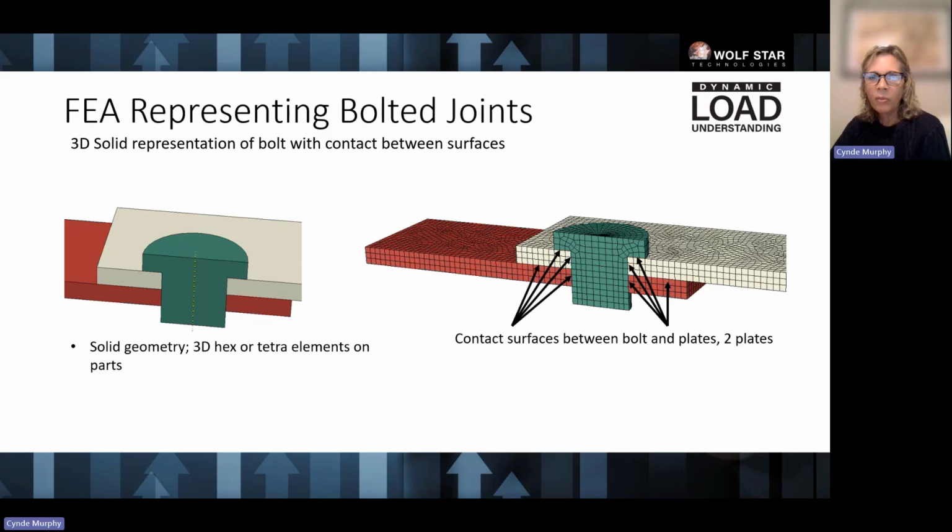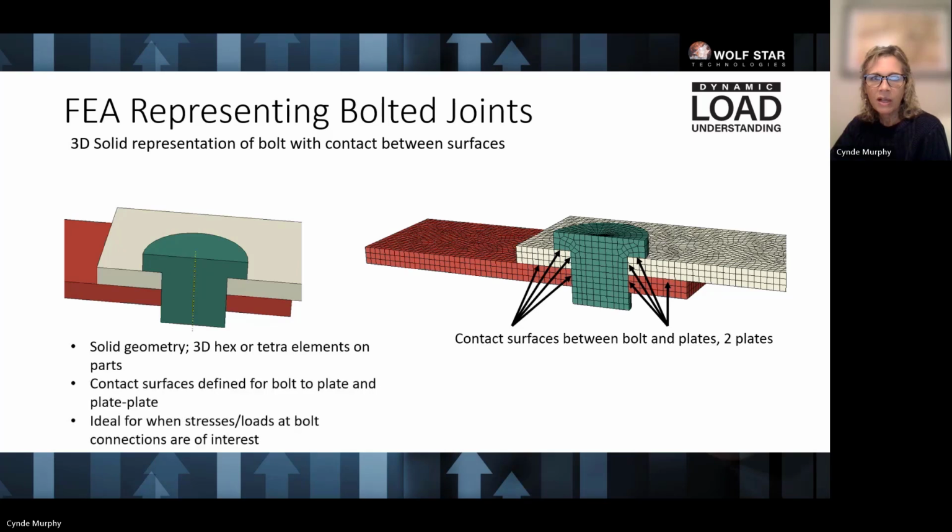All or most of the parts are modeled with 3D or tetrahedron elements for their mesh. Contact surfaces are defined for bolt to plate and plate to plate.